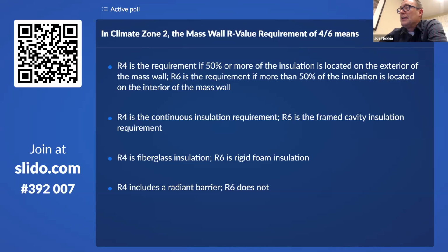If you were spraying enough spray foam to cover the trusses at the ridge line, then you would have some amount of continuous insulation uninterrupted by framing. So if you're only doing the cavity, then you're going to have to meet that R49.